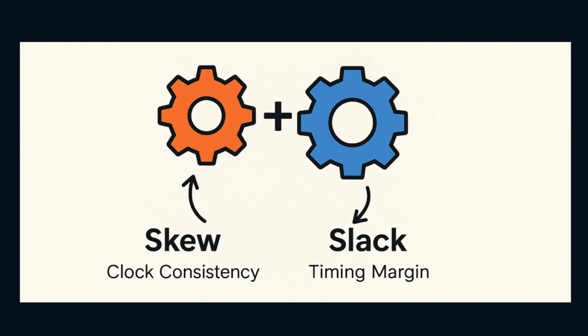That's why positive slack is so vital. It provides that buffer. And designers absolutely have to make trade-offs. Sometimes fixing a setup violation might involve adding logic or buffers that actually worsen a hold violation on the same path or nearby. Or maybe optimizing for speed increases power consumption. It's always a multivariable optimization problem.